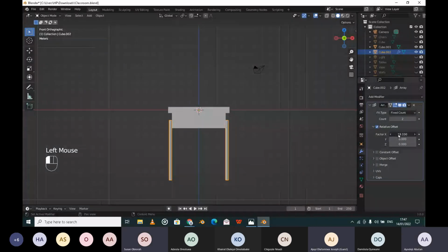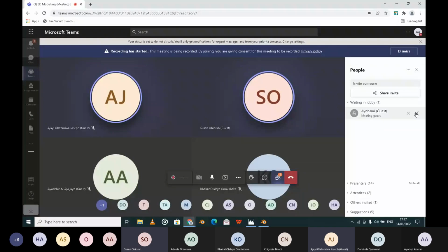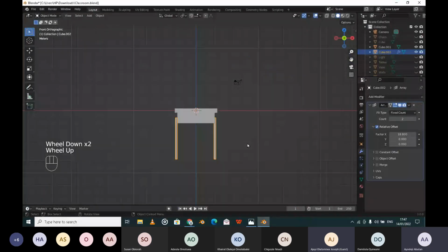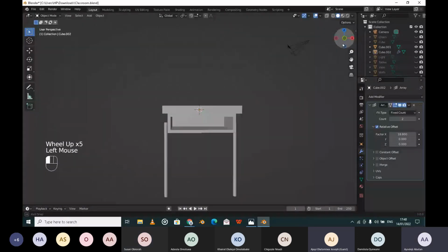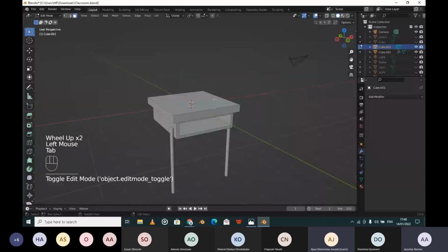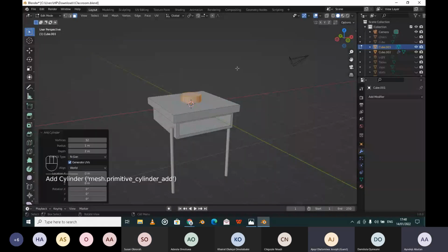So I have a question. Go on. When I did that, it copied both my cube shape and my cylinder. How can I make it go off? I'm coming. I'll show you what you did wrong. Okay, that's exactly what you did wrong. You added your cylinder while you were in edit mode for your cube. Just copied everything. You copied everything on your screen.